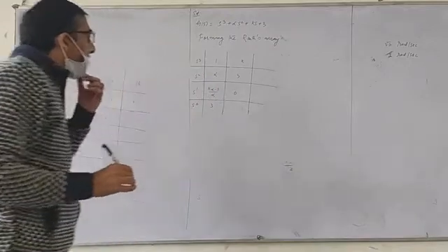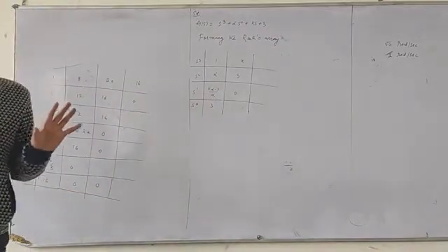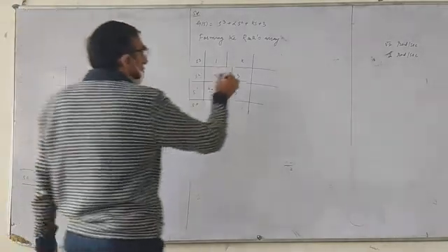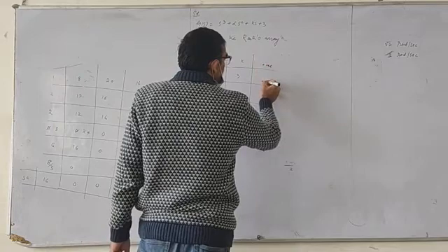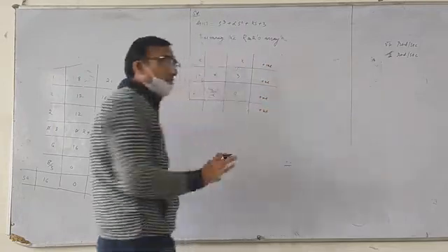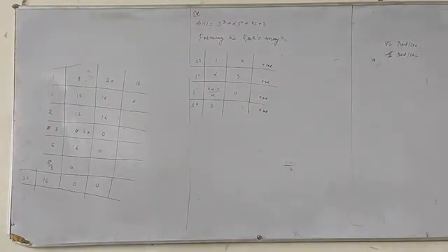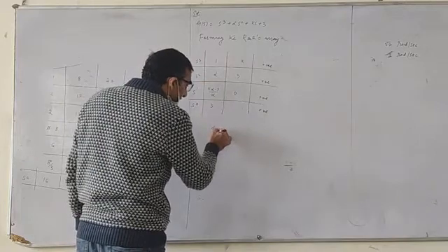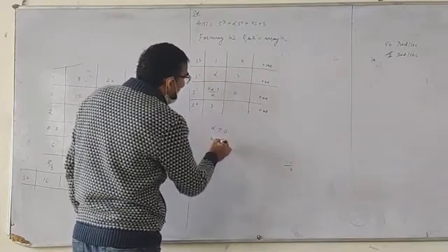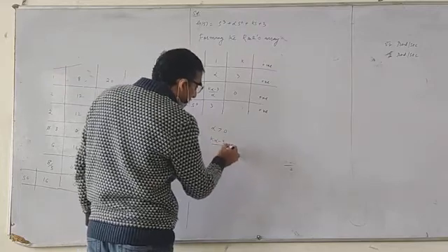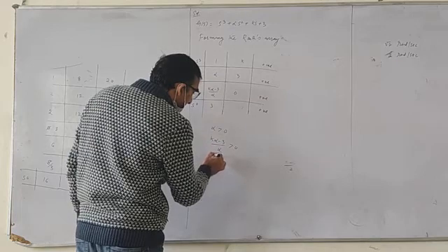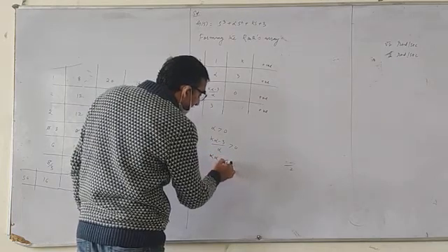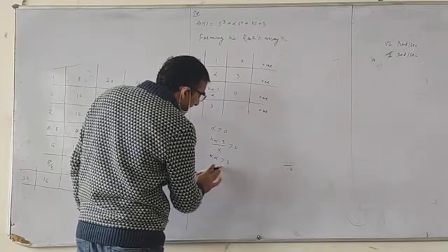So what is the question? What are the constraints on alpha and K? He is giving us a clear-cut instruction that the system is stable. So we don't have to worry, the coefficients are all positive. We know clearly from the question that while forming the Routh array, each entry in the first column has positive coefficients. So the constraints are only two. This has to be greater than 0, and (K alpha minus 3) divided by alpha has to be greater than 0. That means K into alpha should be greater than 3.